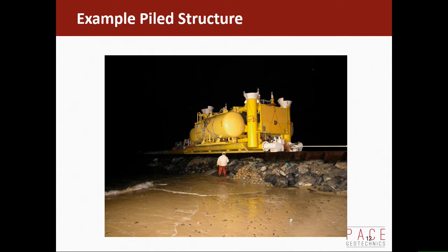When we did this a few years ago now, it was on quite soft clay. So what we had to do was work out how much they could flood the tanks by, so that the structure was stable on the seabed before it was piled, allowed for the weight of the pile hitting the corner, and then piled it in, and then grouted the piles in place. Then they could flood the tanks properly, or I think they actually take them off, but then they had enough weight support to not worry about the structure sinking into the soft clays. And so it was a balancing act, which is what I'm saying.